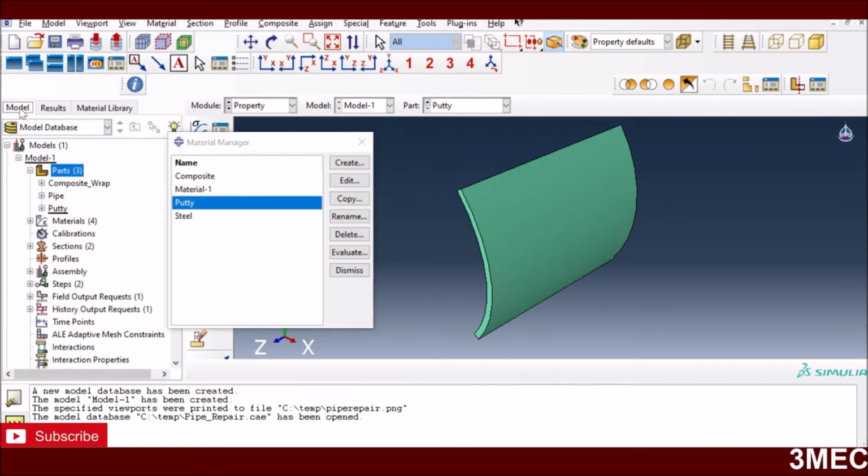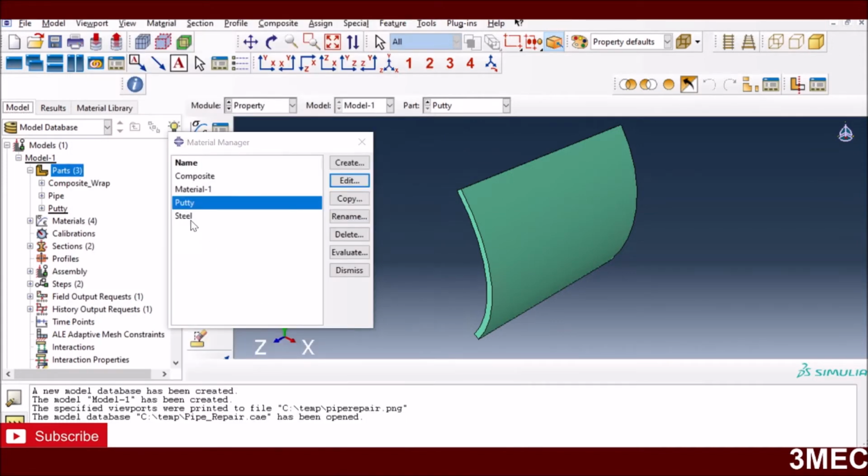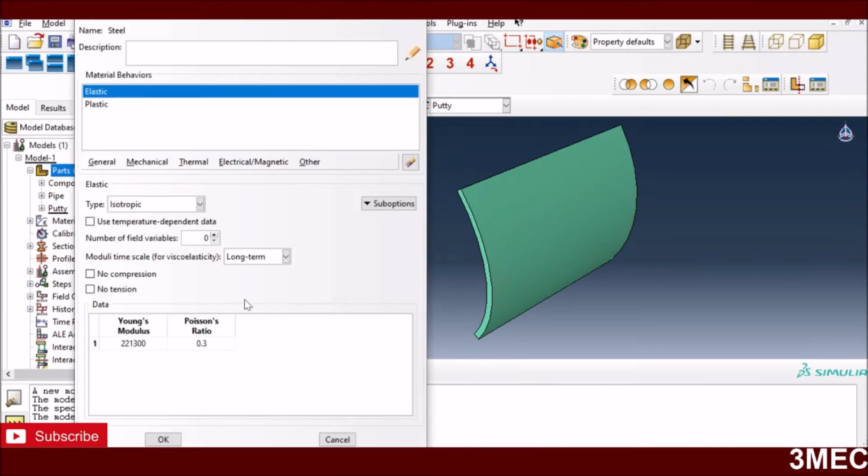Okay, so I go back to the model so that you can see what's happening. Then for Putty, what I have done is, again, I have modeled its elastic properties, and in that paper, they have given the elastic properties of that Putty because they did some experimental test on that. So I'm using those properties here, which is Poisson's ratio and Young's modulus. Steel, very common material, many times I have shown in my tutorials, so I have used the elastic properties as Young's modulus and Poisson's ratio.